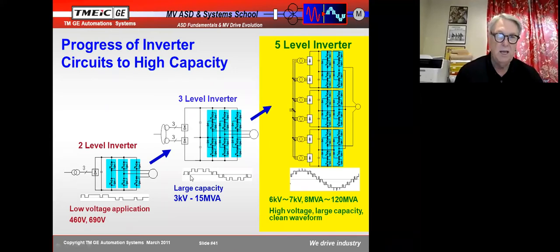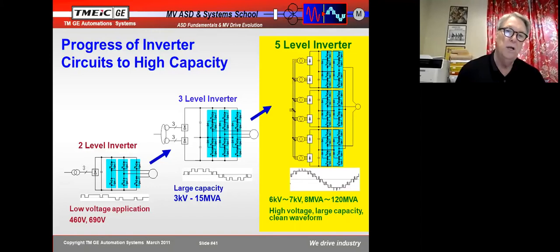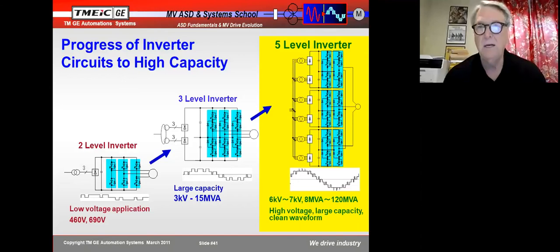You can see in this waveform, 0 is 1 level, then we've got a 2nd level there, which is half voltage, and a 3rd level here, which is full voltage. So now we're only switching on half the voltage at a time, and that is much better on motor insulation. But even half voltage, if we double that half voltage, which can happen in a transient, plus the other half, we're still hitting that motor potentially with 150% voltage, and that's kind of tough.